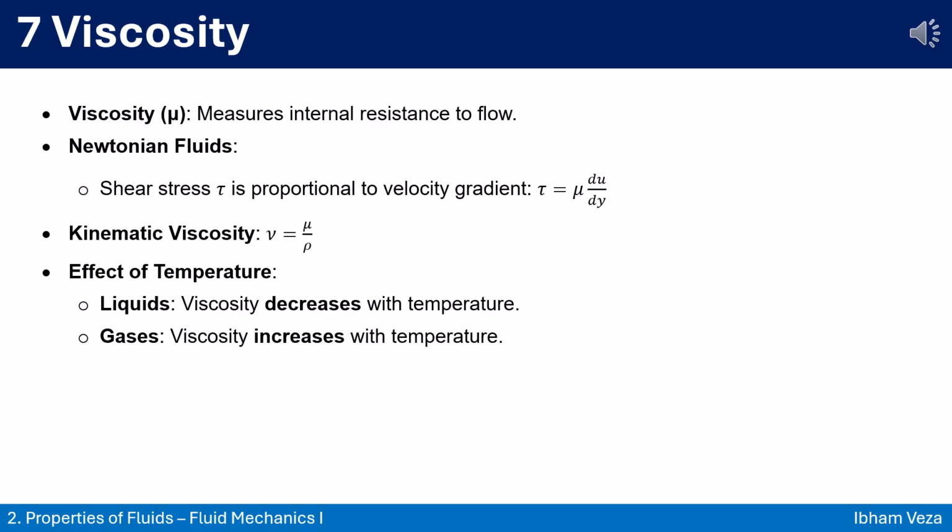Remember this temperature rule. When liquids get hotter, they flow easier, so viscosity drops. But gases behave differently. Their viscosity goes up with temperature. Keep these patterns in mind and you'll never get confused when tackling fluid flow problems.